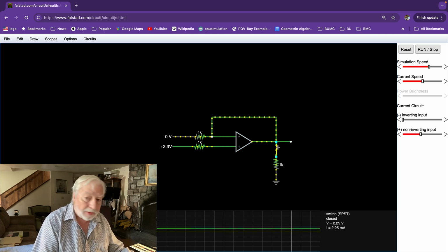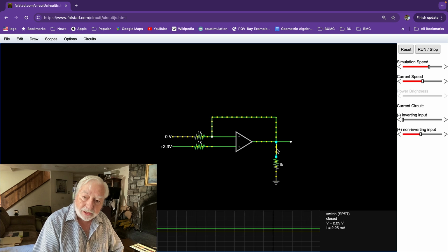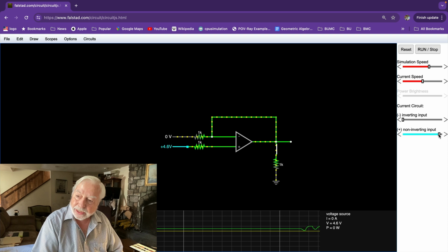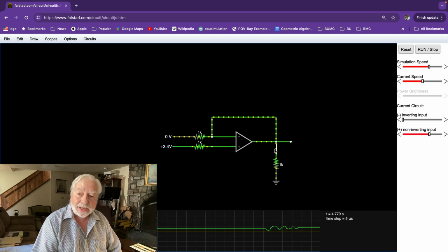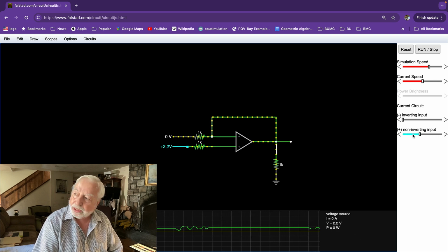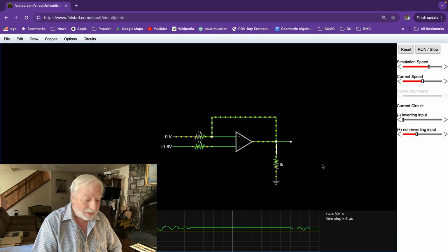If I flip this switch open and closed, you can see that whether or not I've applied the load, the voltage remains stable and it still does its analog following function. So this is functioning like a buffer to make sure that the output stays what it is by this negative feedback, independent of the load that you may put on it.